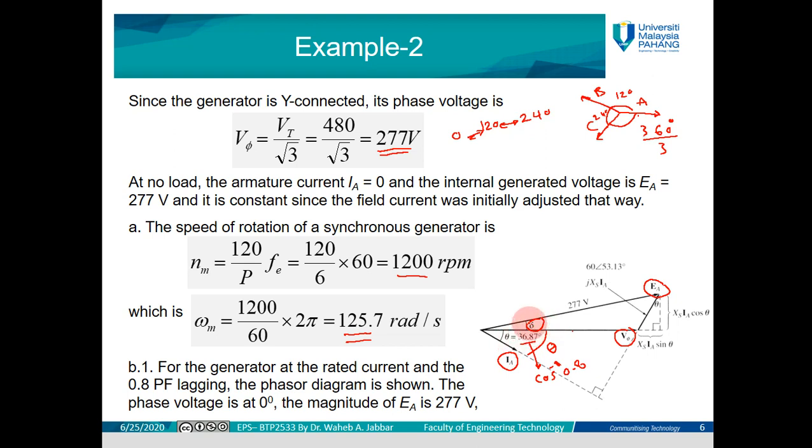Okay, if you remember delta, we call it the torque angle. It is the angle of the torque, or the angle between the phase voltage and the armature or induced voltage. We said that this delta is usually between 15 to 20 degrees, and the base value for delta is 90, and at that point the power will be at its highest value.